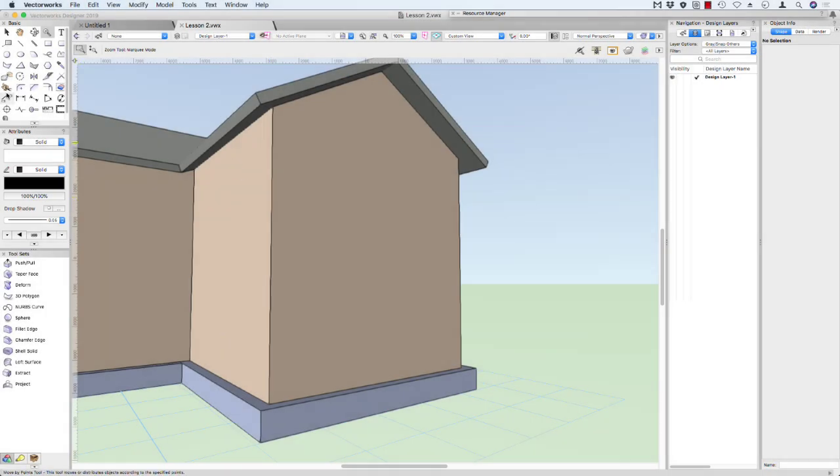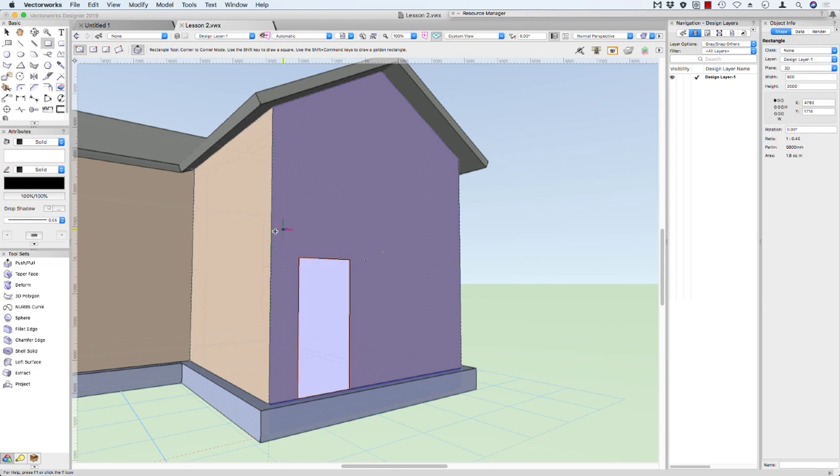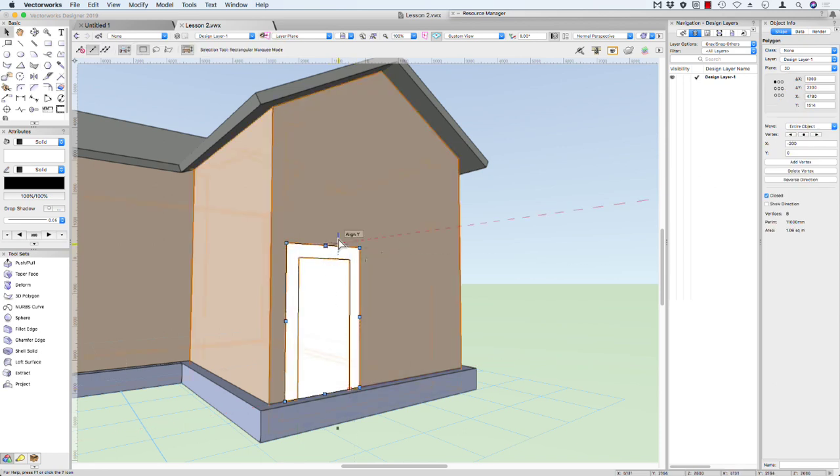So now we're going to create the front door. Use the rectangle tool. This is a technique we've already used previously. So I'm going to click here. My front door is about 900 wide, and it's about 2 meters, 6 foot 6 inches high. I also want to have around that a frame that goes around it. So I'm going to use this tool here. I'm going to use my separation that way, 200 millimeters again, 8 inches. So let's click there. I'm going to come up to that corner, click, click, and double click there at the bottom. So now I've got a few bits and pieces.